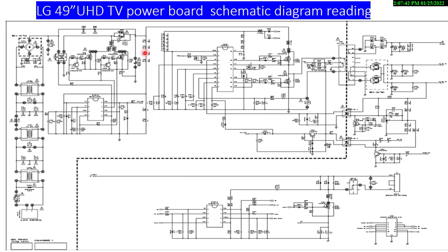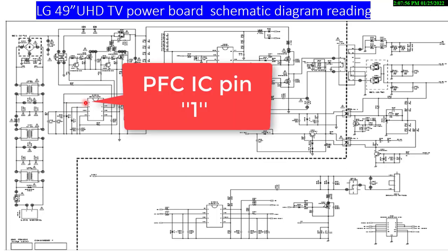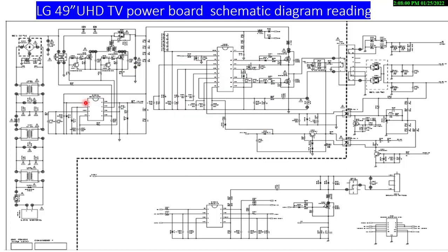After the filter capacitor, look, this line is coming to the PFC IC. Look at this one: the line voltage for the PFC IC. The other one is for the multi IC. So this point is one critical point.